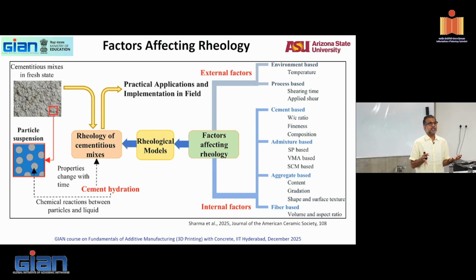But what are the factors that you think will affect rheology the most? If you are asked that question, what will you say? Give me one factor, what will be the most obvious answer? Water cement ratio, like strength, same thing, right? What will affect the strength the most? Water cement ratio is a perfectly good answer. Okay, water cement ratio, take it. What will be the next thing that will affect the rheology the most? I assume that I'm keeping everything at a constant temperature. My lab is all well controlled.